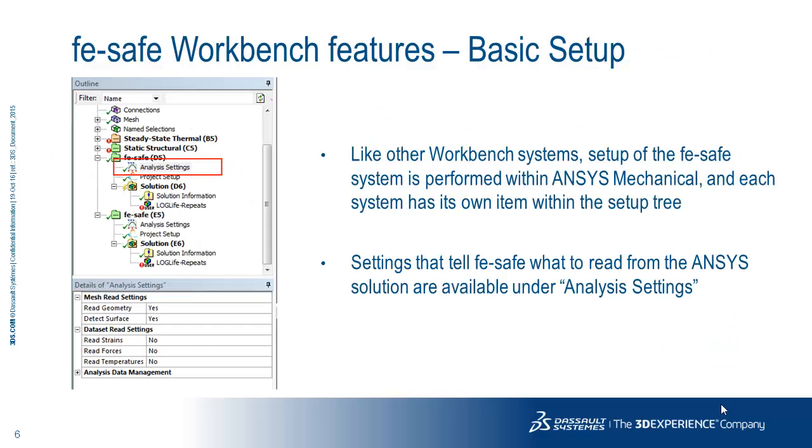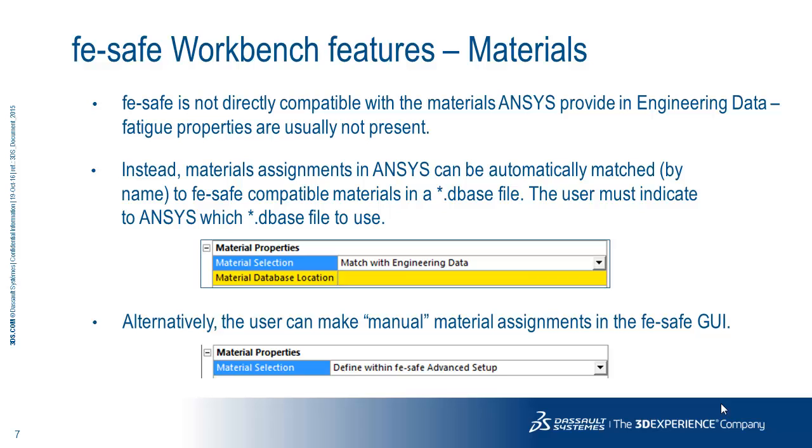Also, in the FE-SAFE Workbench, there are different options, and one of the options is the analysis settings. In these analysis settings, you can choose whether you want to read strains, forces into FE-SAFE or not. So directly from ANSYS Workbench, you will be able to do that. You can also choose the material.